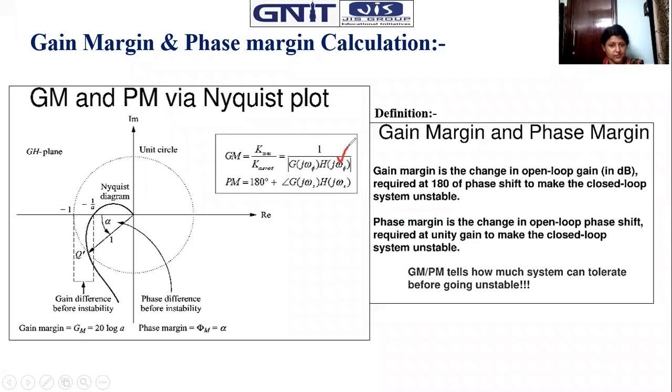But here we are getting N equals 2. So we need to find what will be the number of zeros existing at the right-hand side. That is basically 2. If we put the same formula here, we get Z equals 2. That means we have two right-hand side closed loop poles existing in the system. So the system is unstable, and for the previous case, the system is stable. So that is the total procedure.